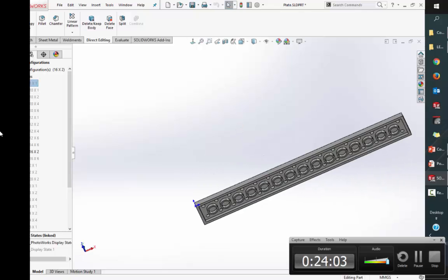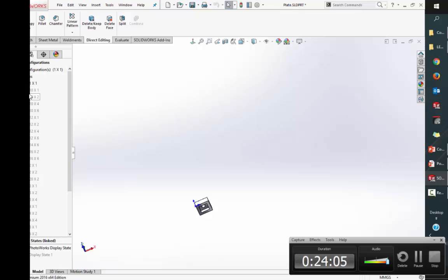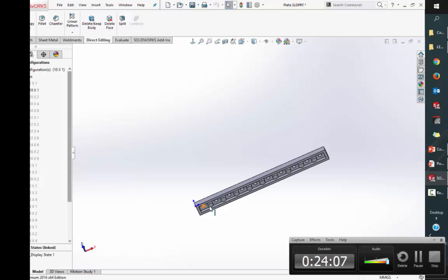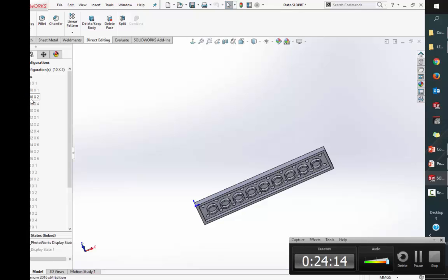And meanwhile, what's happening underneath here is you'll see that certain things are changing. So you'll see that there are little pegs there, but if I go to a 10x2, you will see that there are little barrels that are going to show up underneath here. And so now there's the barrel. So basically what I'm doing here is in my configurations, I have to control the numbers on my patterns, the X by Y. I have to control whether that feature is on underneath. And then I have to control the number of that feature, because that's always 1 minus however many I have. So if this is 10 little things wide, I only have 9 of those in the middle. So there's a lot of variations that are coming in here.